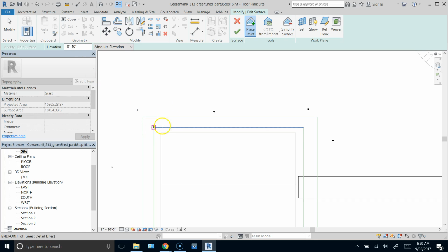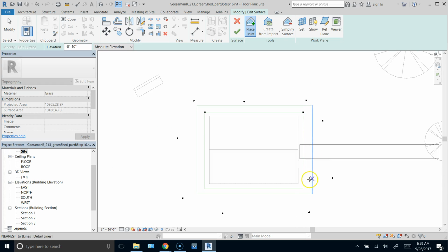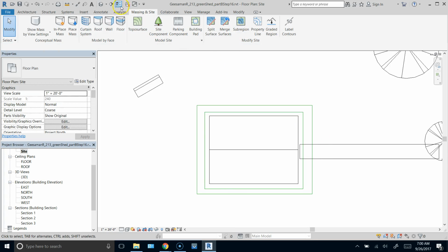And those points are going to be at the corners of this first rectangle. Now I'm going to come down to our -1'6", because that's where our soil is right now. And I'm going to force these, and it's okay that I'm over placing points. This is already 1'6", but I want to guarantee that this 1'6" here is right on my rectangle. Now green check mark and finish.